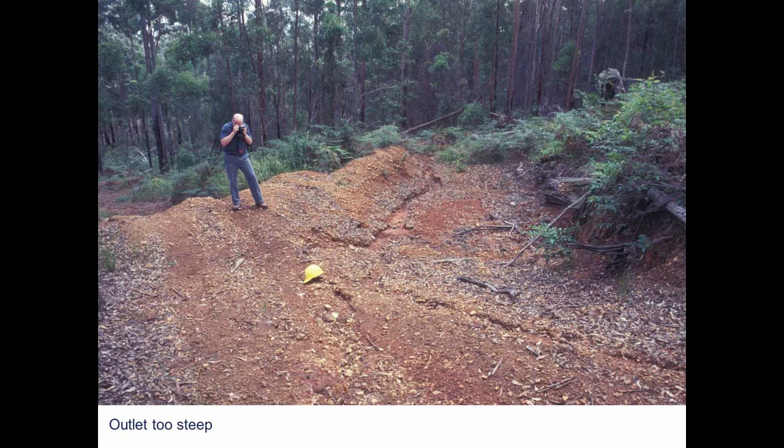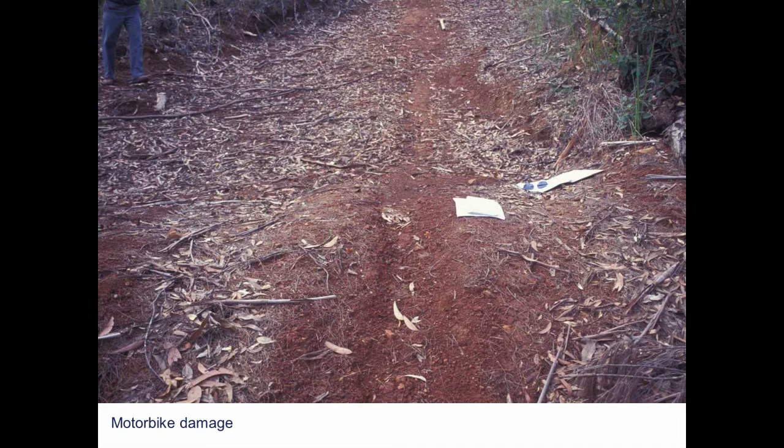Another thing, not picking on motorbike riders, but it's a maintenance issue, is that these things need to be constantly checked and maintained, because whilst you can have a really effective and even large rollover bank, it only takes a bit of wet weather and some motorbikes or mountain bikes or anybody to breach the top of that cross bank or rollover drain, and it becomes ineffective. So again, it's a maintenance issue. These things need to be checked fairly regularly to make sure that they're not being exceeded, because in this particular case, if it's a steep track, that indentation there is basically a breach in the top of the bank and can create an issue where water will overtop the bank and then erode further down the hill slope.